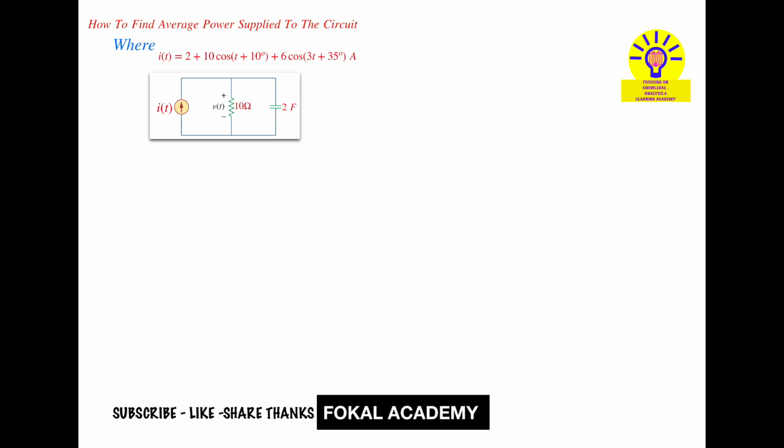This is the problem. So here we want average power. For calculating average power, we need both current and voltage. Here we have only current, but there is no voltage source in the circuit. So first of all, how can you find the voltage V of t? In the first step, find the overall impedance, and from that we can find the voltage. According to Ohm's law, V equals I Z, where I is the total current and Z is the total impedance of the circuit. From this we will get the voltage for the given circuit.